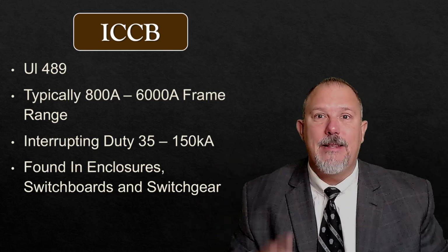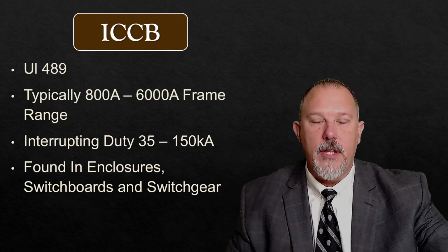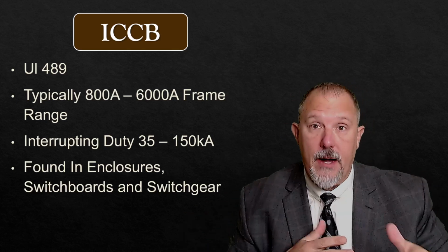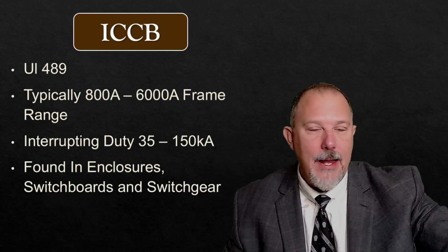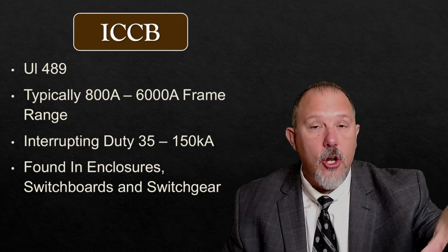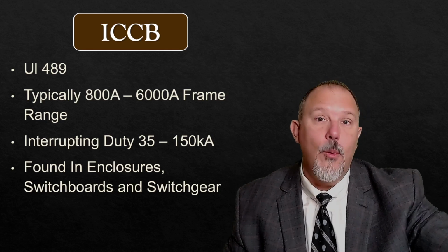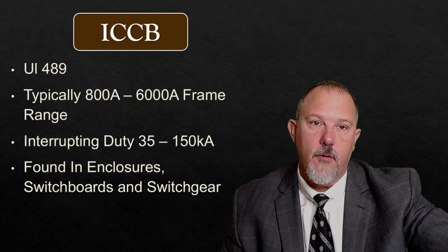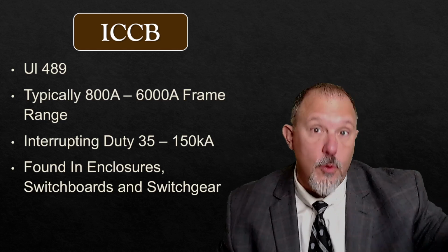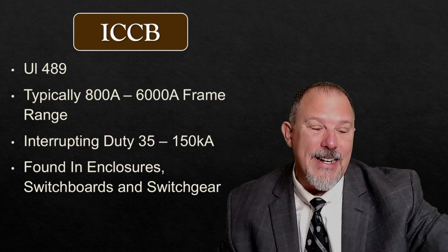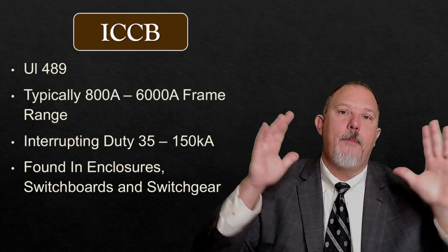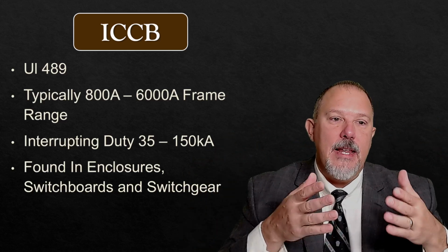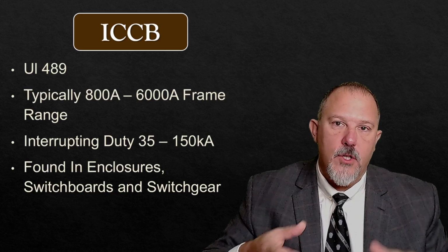Leadership is not micromanagement. It's not about telling everybody what to do. It's not about shutting the plant down the moment one little issue happens in a plant and making everybody run and scurry. It is about letting the overcurrent devices closer to the action do what they do best. Think on their own. Respond to those overloads. Respond to those short circuit currents. Respond to those ground fault currents. And isolate the problem without disrupting the entire facility. The insulated case circuit breaker gives me the ability to hold those contacts closed.